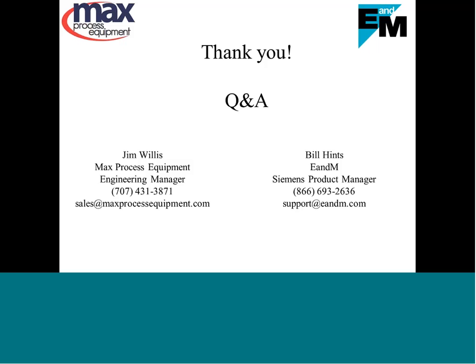There's one other question here. I'm going to answer by email. It's going to get a little involved there. One more thing, follow up on the bias. So the question is about bias and transitioning from manual to automatic mode. It's called bumpless transfer, and this is where we do use bias. And actually, what we're doing is we're getting into the innards of the PID algorithm, and although we don't need to do that with TIA, we still have access to them.